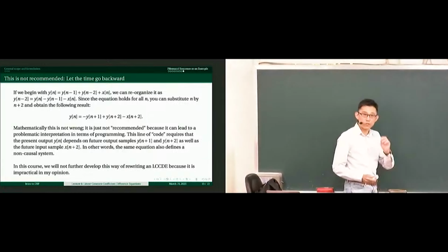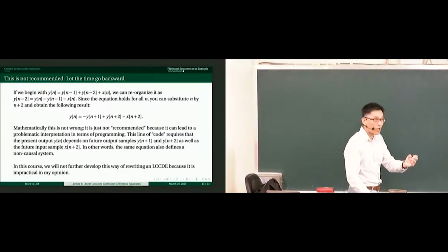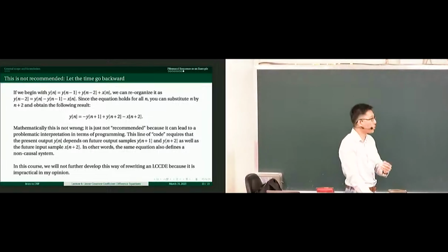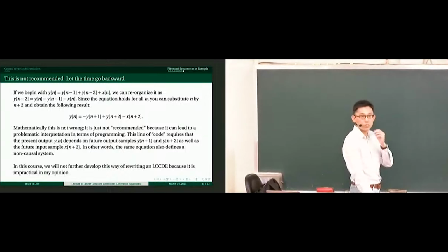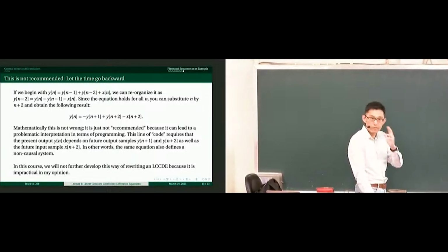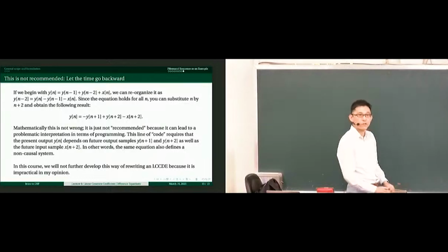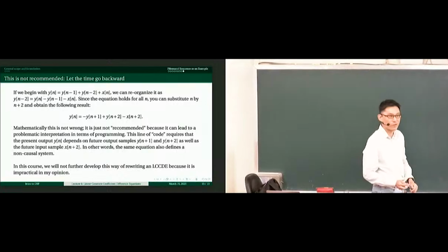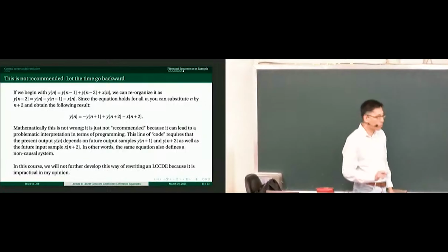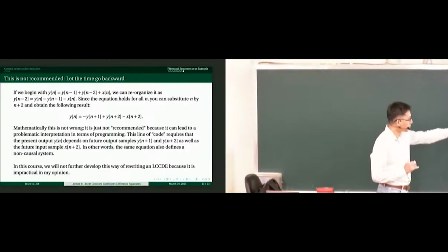Okay? So it's a difference between whether you're storing the file and loading it for post-processing, or whether you deploy your system in real-world, real-time applications. There could be an exception: in post-processing, maybe you can allow the time to go backward. Fine. But that will make your life tougher when you talk about the z transform and stuff. So in this course, we stick with a simpler idea. We confine our interest to only talk about causal systems. Okay?